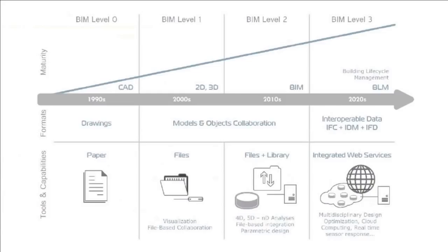I think with both Revit and Vectorworks, and my main experience is with Vectorworks, you do the conceptual design, probably not schematic, you just do that by hand, but you do the CD, and that same model matures through the whole process until you're down to cutting sections, detailing and annotating. For any kind of BIM platform, that's the idea: you don't have to switch back and forth.